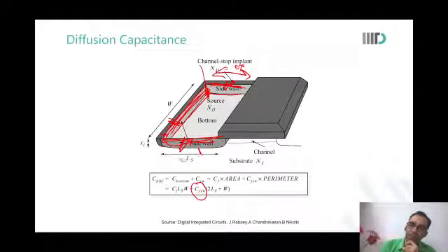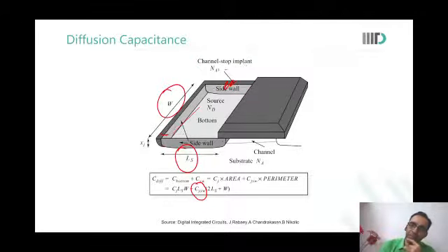So this is LS, the extension and the width. That will give me the area of the bottom rectangle, and I multiply that with C junction. With this, I get the overall diffusion capacitance of the drain or the source region.